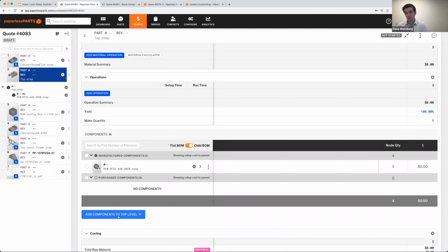What we see in terms of best practices is that if something has a child component that is manufactured, something that you actually need to make, whether it's a machine part or a fabricated part, then the parent should be called an assembly, and that aligns most directly to the definition of an assembly in ERP systems and manufacturing at large. So we usually recommend that you use the manufactured component with subcomponents for things like parts with hardware. And anything that's more complex, where you actually have parts beneath it that you need to assemble together, that's when you should use an assembly.